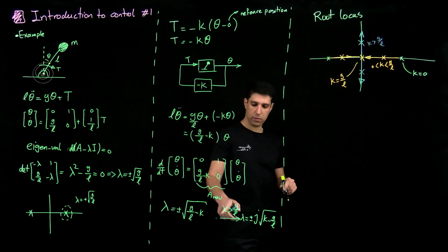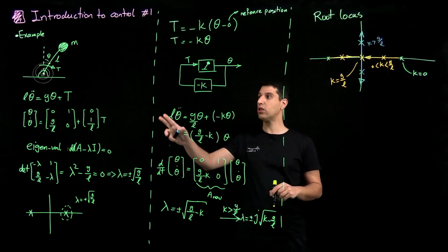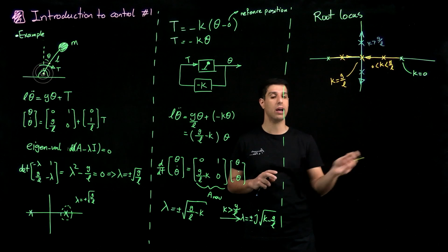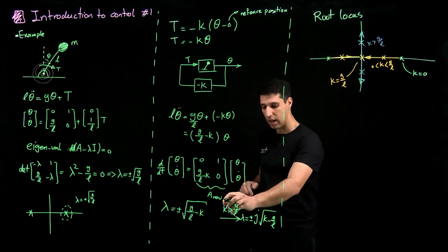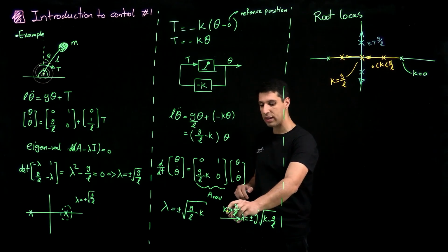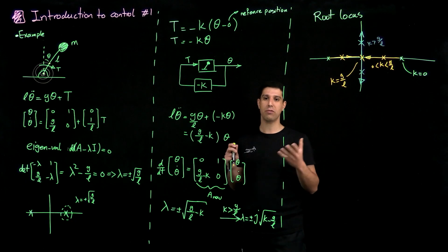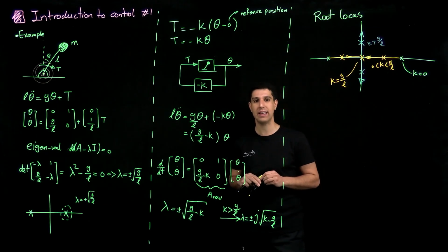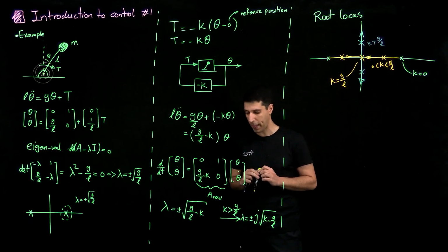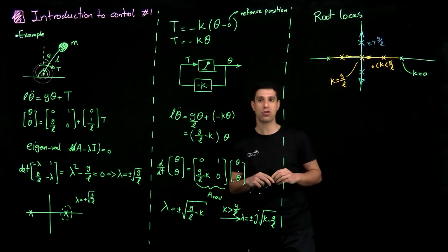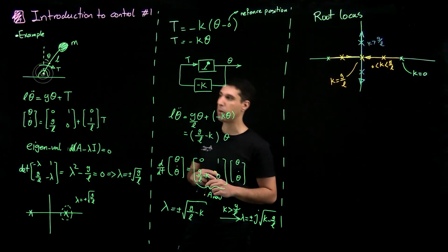I mentioned it, but not explicitly. In order to stabilize the system and move it from unstable to stable, you need to have a control gain that is at least bigger than G over L, the strength of instability of the actual system. So you want your feedback loop to be stronger than a certain amount to be able to stabilize the system.